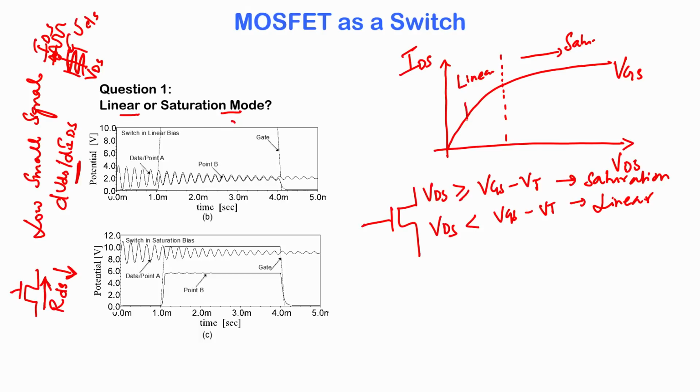We have set a VDS and now we are going to fluctuate a small signal vds around this, and we are going to see a fluctuation in the current in response to that. So, this slope is essentially the resistance. As we move the voltage up and down, the current moves up and down, so the current changes by that level, and therefore the resistance here is some value which we will call R linear, which is your dVDS by dIDS.